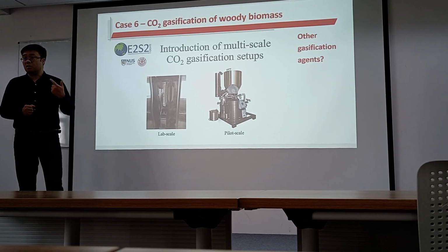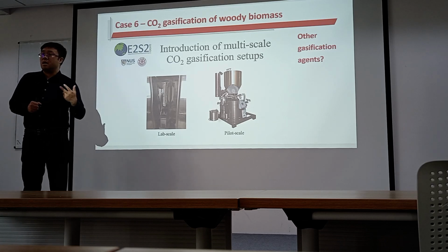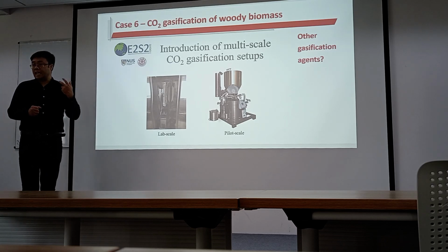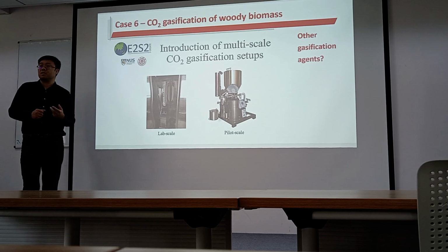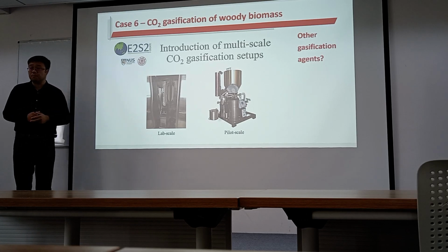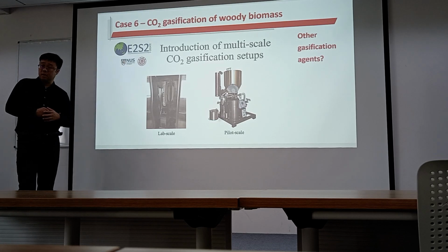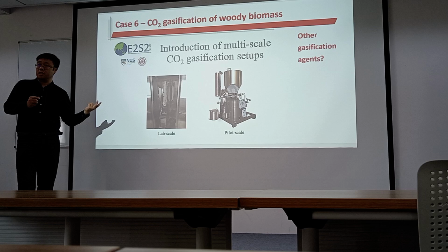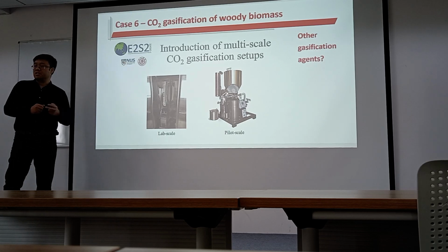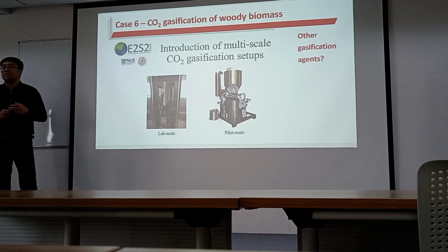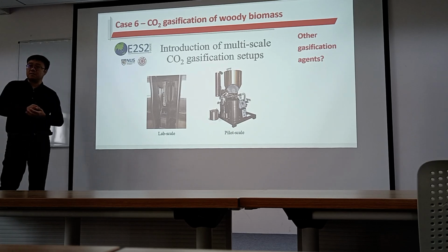Air, oxygen, and steam are three major gasification agents that we use in the gasification process. Because oxygen actually is not easy to separate, in this case, the air and steam are two major gasification agents that we commonly use in this process.